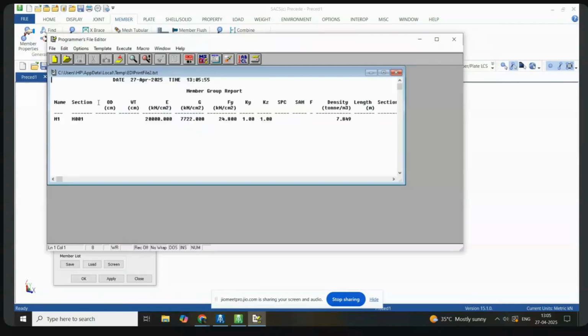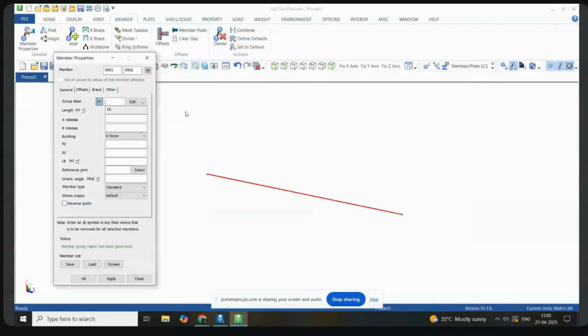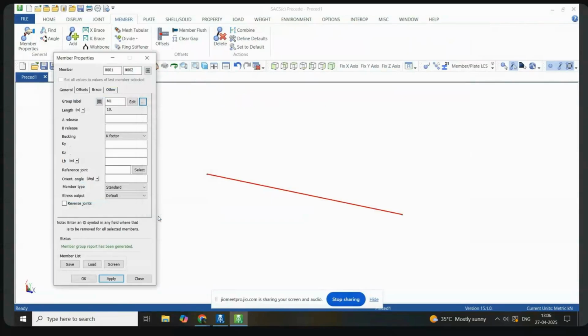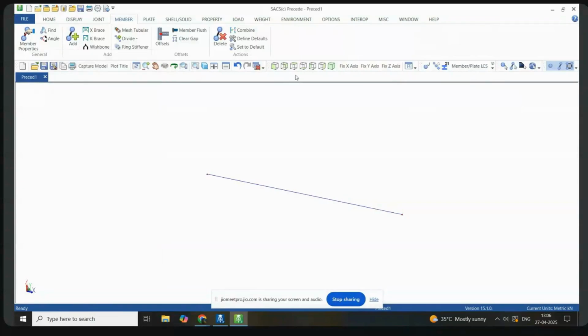to the three dots after edit. No, you close it there. You come to three dots after edit. Click on M1, assign, and apply. Now your member is assigned. If you go to 3D, Ganesh and Arun, please hold on, I will come to you. Next. 3D. Next button. Yeah, that button. See, your 3D came. This is how you assign.